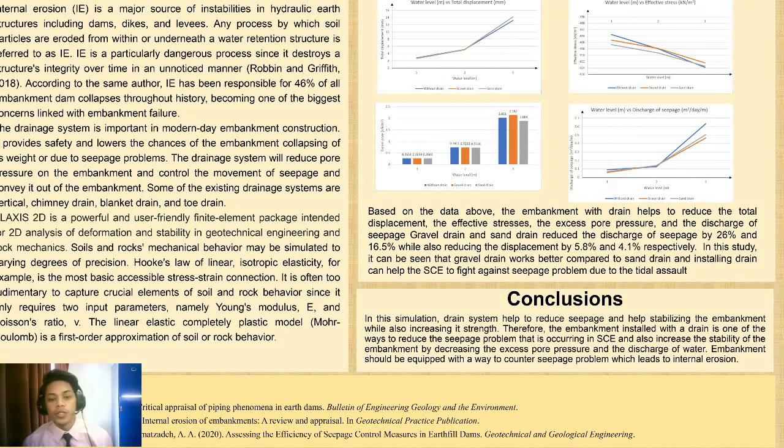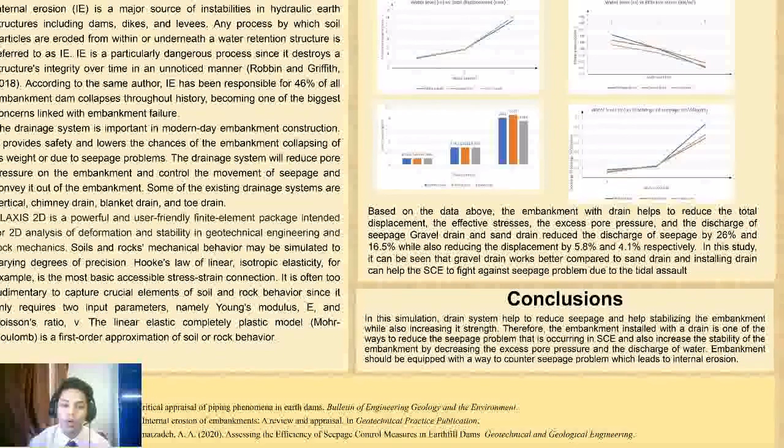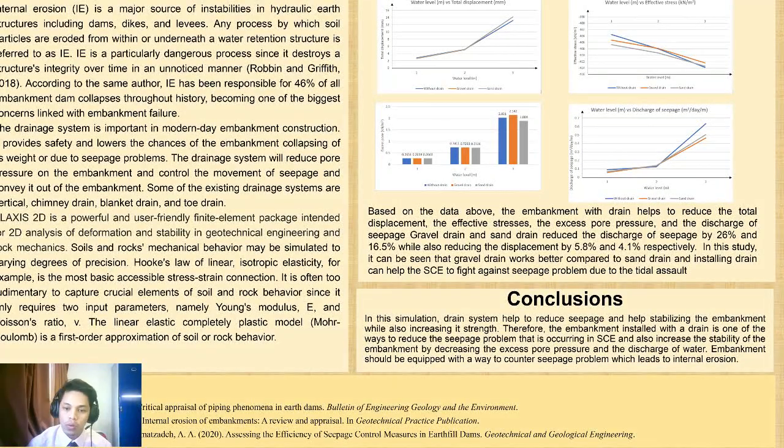Next is the conclusion. In this simulation, the drain system helps to reduce seepage and helps stabilize the embankment while also increasing its strength. Therefore, an embankment installed with a drain is one of the ways to reduce the seepage problem that is occurring in Senggarang Coastal Embankment, and also increases the stability of the embankment by decreasing the excess pore pressure and discharge of water. Embankment should be equipped with a way to counter seepage problems, which lead to internal erosion, and the answer to this question is